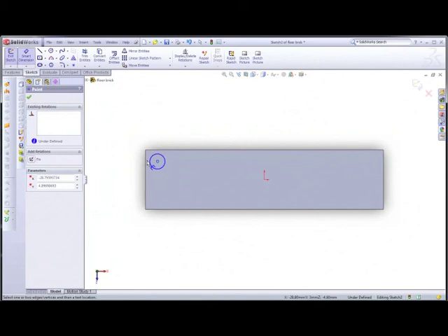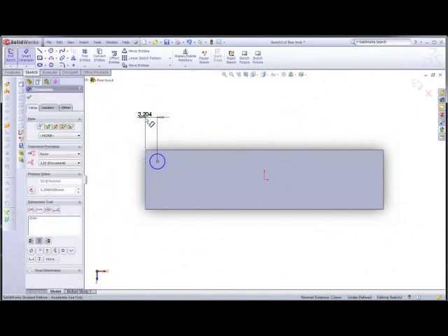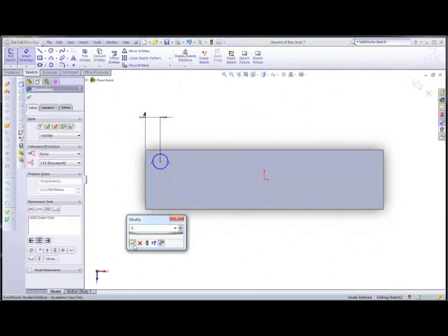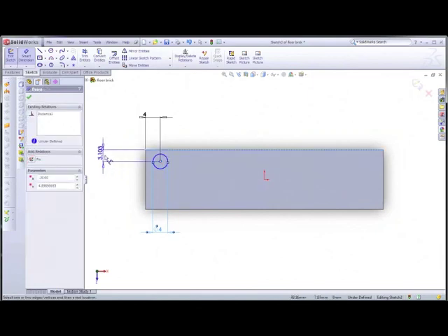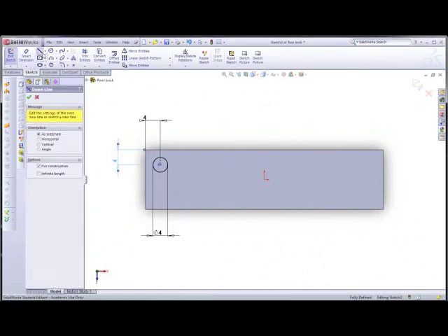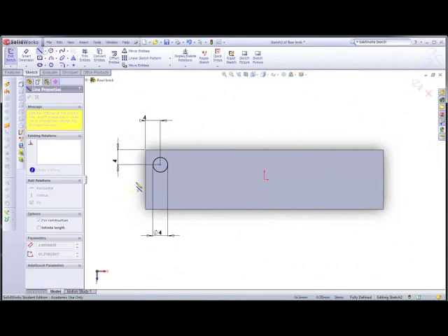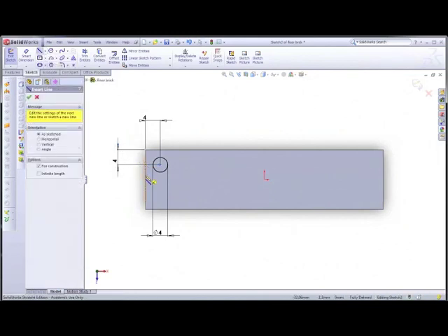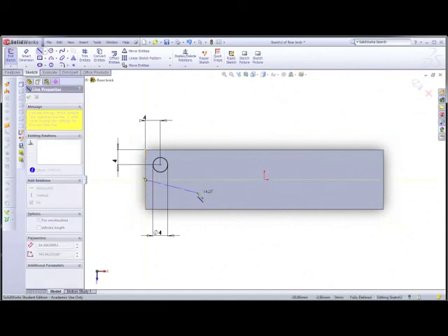So again, from there to there is 4 mil. Oh, the radius I haven't done, sorry, the diameter again is 4 mil. Always make sure, guys, within Solidworks you're constantly dimensioning things. It's really important to remember that. Okay, so 4 mil again, green tick. Okay, now that's ready. Now again, I can add a centre line down the middle, so press escape, there we go, centre line, and then I click down, hover down, wait for that orange bit to come up, select that, and select that point.